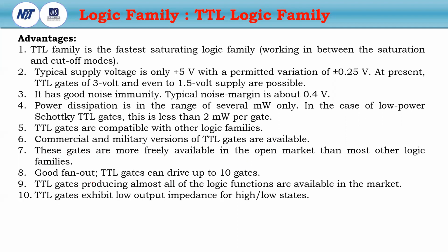It has good fan out. It can drive up to 10 gates from a single gate. So this is the fan out, which is very important. For TTL gates, the maximum fan out will be 10 gates. TTL gates producing almost all the logic functions are available in the market. TTL gates exhibit low output impedance for the high or the low states.